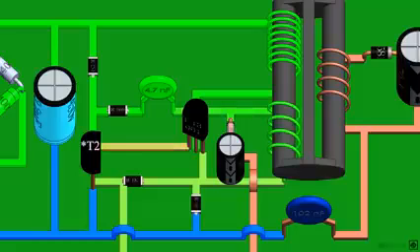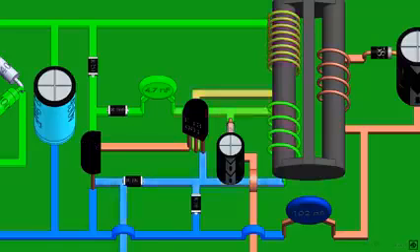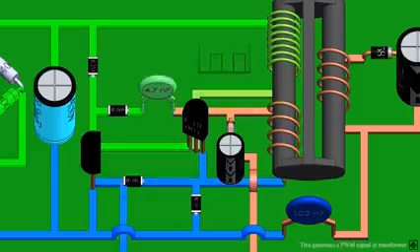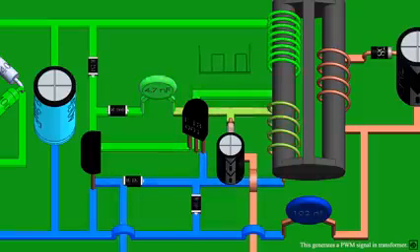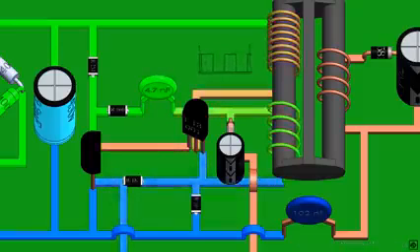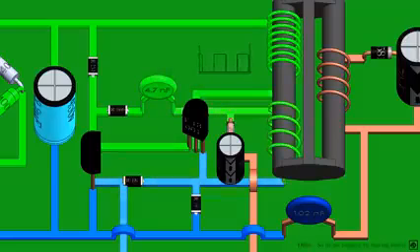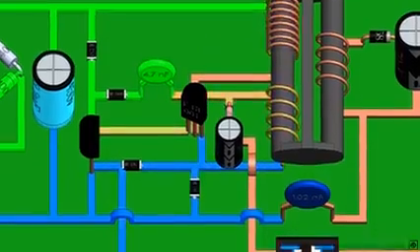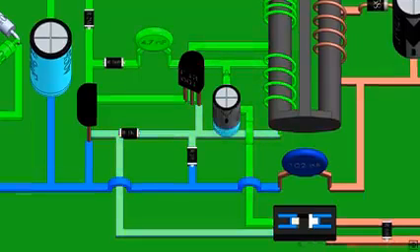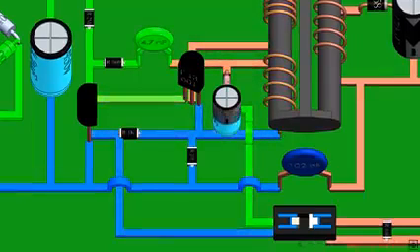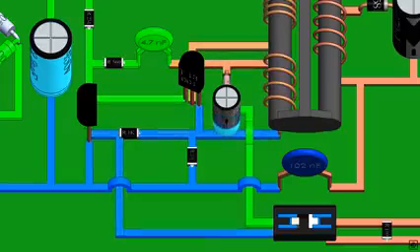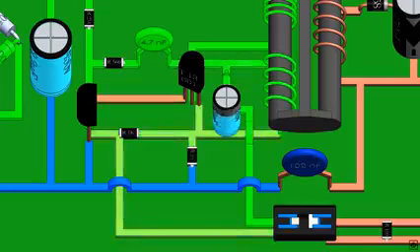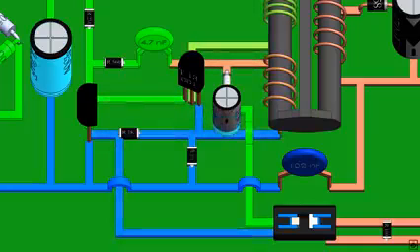This shunts the base of T1, turning it off. As T1 turns off, the flow of current to T2 is cut off. Now the current flows to the base of T1 and the cycle repeats. This happens at 15 to 50 kHz, which is 1,000 times faster than the rectifier circuit. Hence, you would see that the rectifier circuit appears stopped. At the same time, the voltage from the auxiliary also turns the diode on and charges the capacitor and flows to the optocoupler. This diode and capacitor convert the AC from the auxiliary coil to DC for the optocoupler.